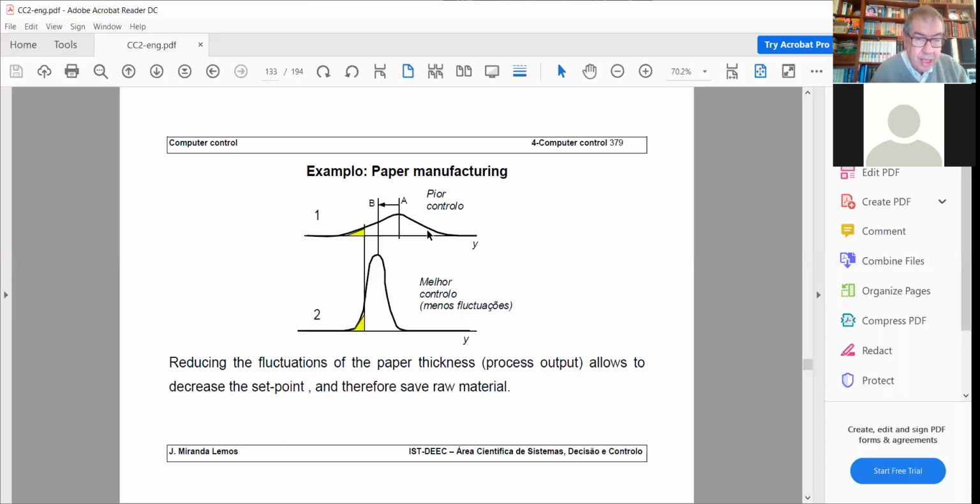Okay, so the set point A for your process is not at 80 grams, but above 80 grams. And it is such that the area under this probability density function, think of it as a histogram, is 90%. And you are violating only the yellow part, which is 10%.